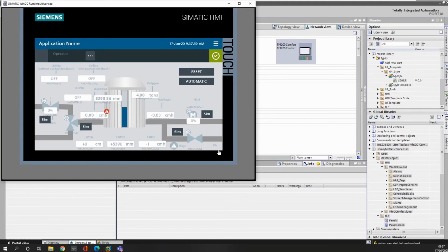But there may be times where you've got your SCADA running your plant, but you want a little bit of local control, so you want to put an HMI down on a local bit of plant. As this library does not only include the graphics objects, it includes all the blocks that actually go inside the PLC, if you've used it with your SCADA, all those blocks are there and available inside your PLC. So why not use those blocks to build displays in your HMI?